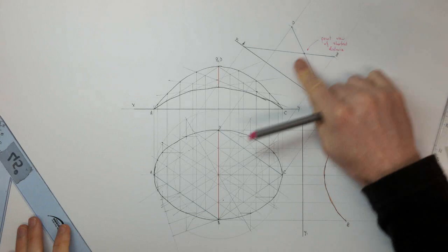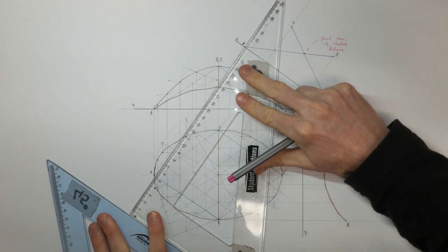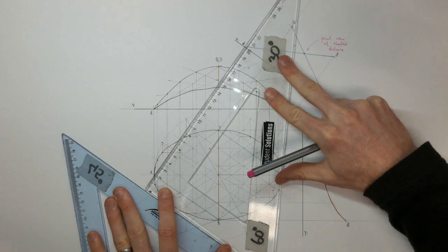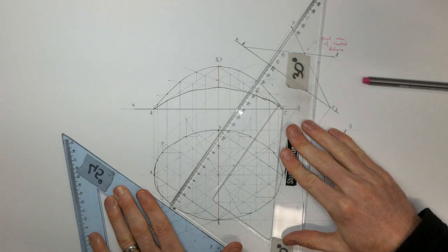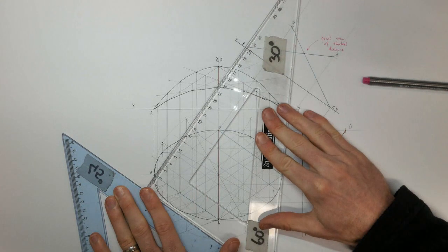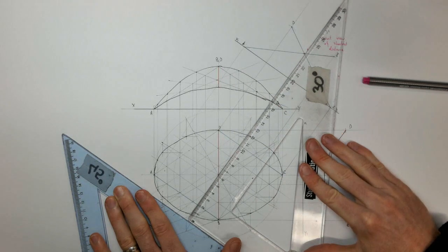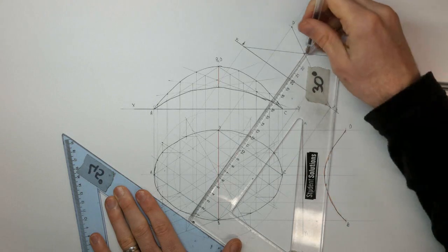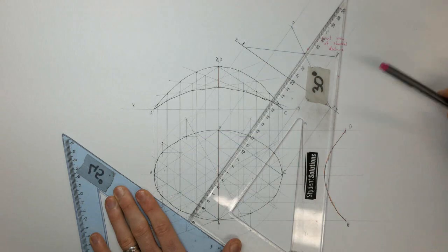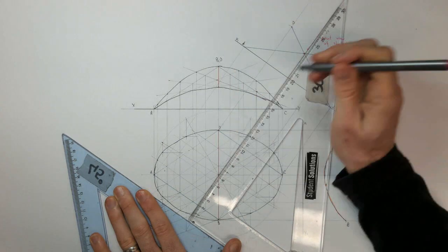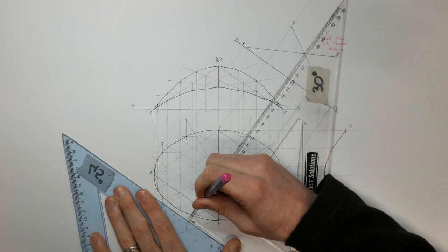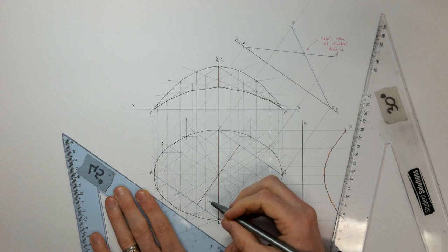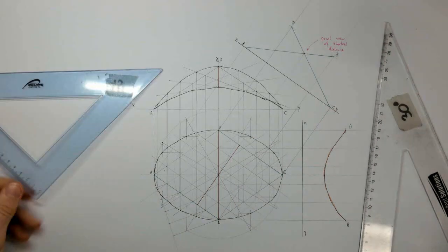So we are going to project that back onto our plan view. So I'm right through the middle, interesting enough. And that is the shortest perpendicular distance, or shortest distance between skew lines.